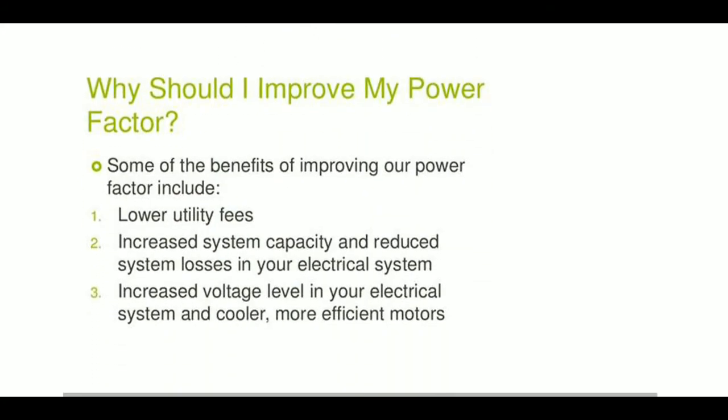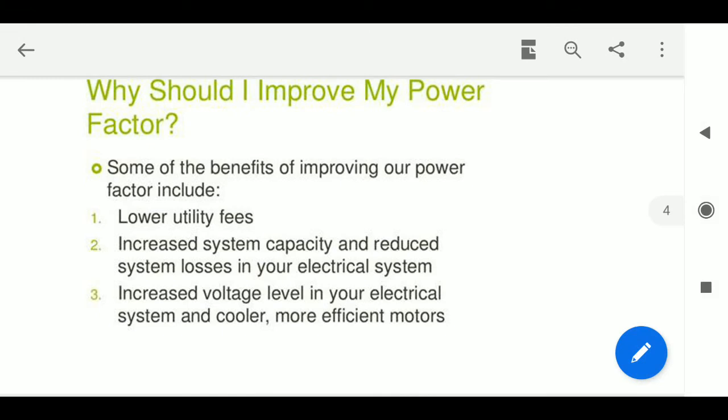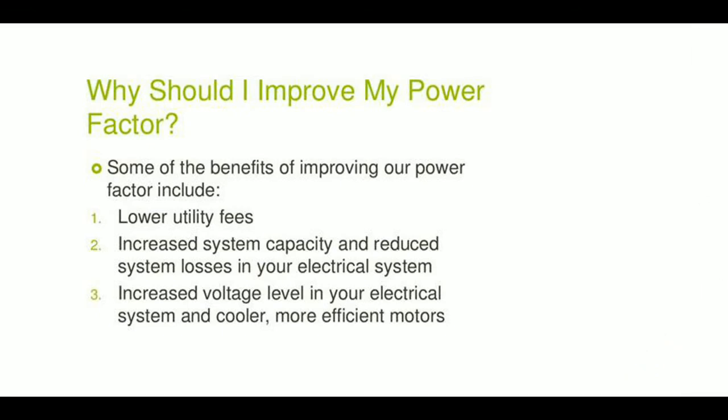Why should we improve power factor? Some of the benefits of improving power factor include lower utility fees, increased system capacity, reduced system losses in your electrical system, increased voltage level in your electrical system, and cooler, more efficient motors.